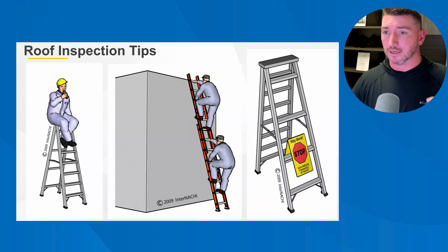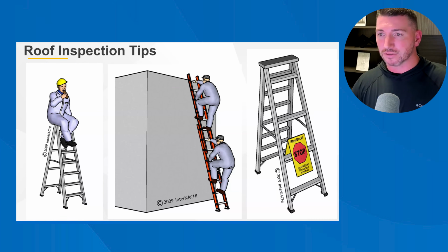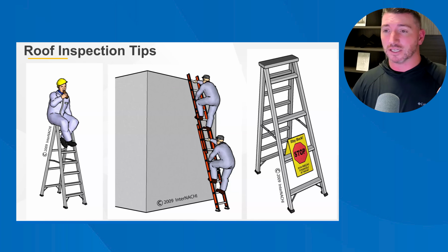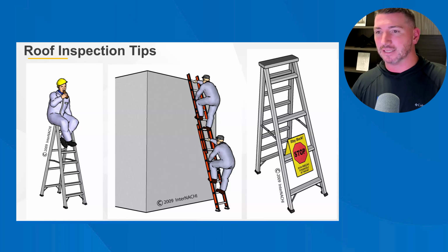If you see that there's a modified truss in an attic space, I would call it out immediately as a material defect. And what your verbiage should say in the report is, this is a material defect and needs to be evaluated immediately by a licensed professional structural engineer, unless documentation is provided that this change was made by someone with the sign off of a structural engineer.